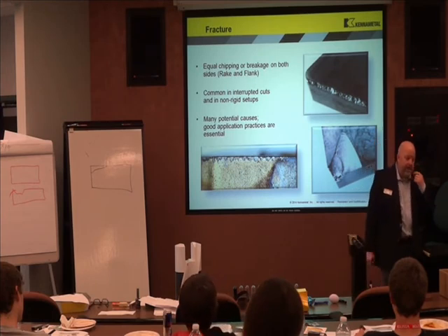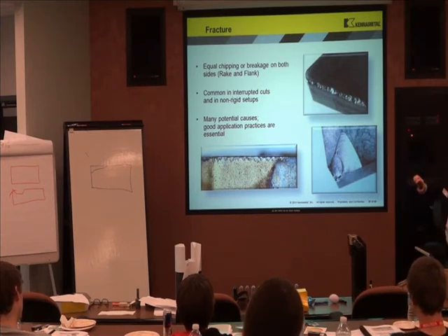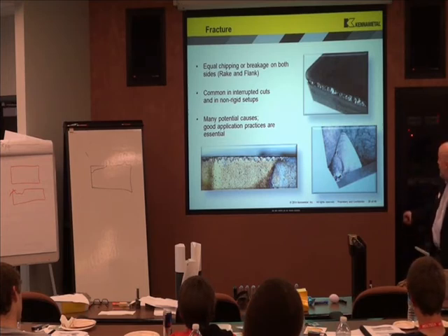Last but not least is it broke. See how this looks like a rock surface? It doesn't look like somebody scraped it. It looks more like a rock. That broke. When an insert breaks, usually I tell them it broke. Inserts don't break on their own. One of those other failure modes was typically happening before it broke.